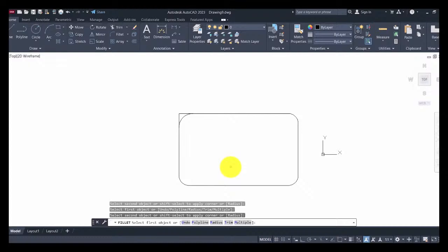Okay, all right now. So I've been able to add fillets to the corners of the rectangle. So no more sharp corner. So now I've applied fillet in 2 ways. I have used no trim setting here, whereas for this other 3 instances, I used trim setting. Then I'm sure you must have learned now how to measure your fillet radius. You can either measure it or you have dimension depending on what you have. All right, so that's fillet.